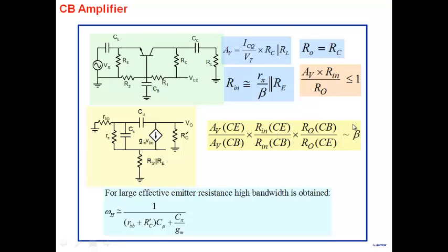We also saw some applications of lower input resistance. But the main motivation for going towards common base was not the gain and the output resistance, but the fact that there is no coupling capacitor between the input and the output node, so maybe Miller's effect would be absent there, and we would get very high bandwidth.